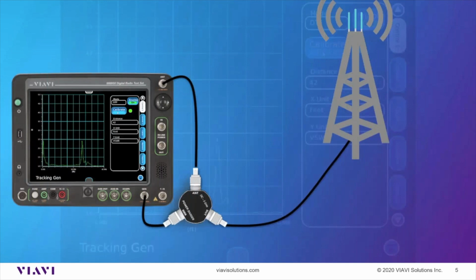If that distance to fault runs all the way up to the antenna, I'm going to show you what the antenna looks like here in a minute, then the antenna is bad. But if the distance to fault only runs part of the way, of course, you kind of have to know the distance from the base station to the top of the tower. That's something you'd have to know.